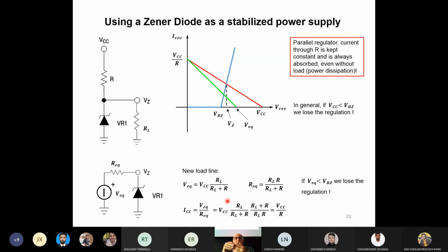How can we do that? And we saw that we can use a Zener diode, we can use the constant current generator, the one with the two transistors, or the band gap reference. I told you most of the time, if you want to use this like a voltage reference, we are not going to take any current from the voltage reference circuit. So they are used without any current.